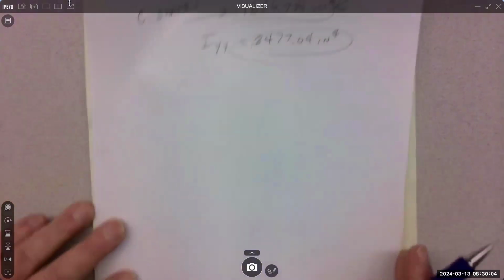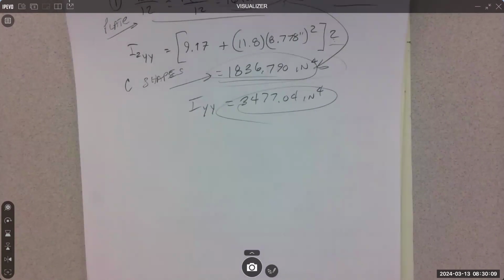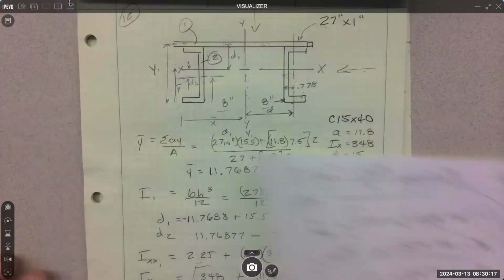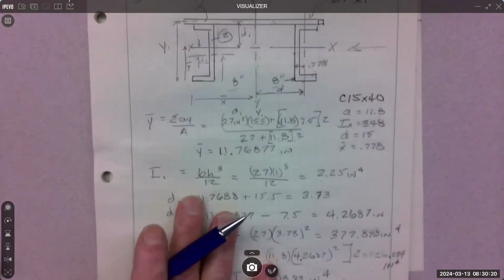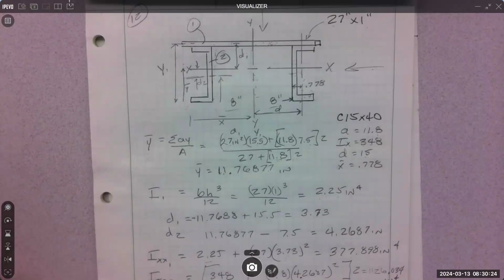So when your two-axis inertia is pretty good in both directions, then its ability to resist twist is also very good. So any kind of box section, and this is a little boxy. Put that plate also on the bottom and you'd have a heck of a strong structure.